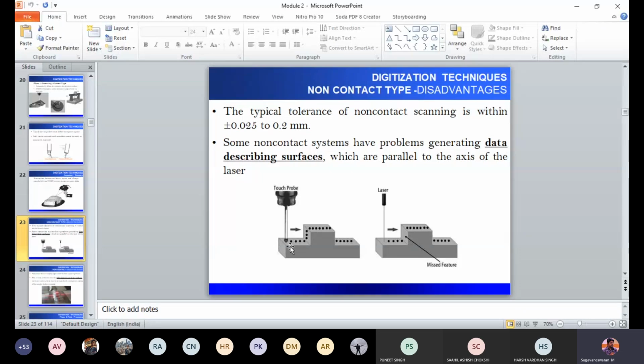This point is 3, 2. The third point is 4, 2. The fourth point is 5, 2. So as I touch multiple positions, I am able to measure the distance between the previous position and the current position, and all those positions will have a reference to the home position which you have touched earlier. So you can easily measure the dimension using this method.